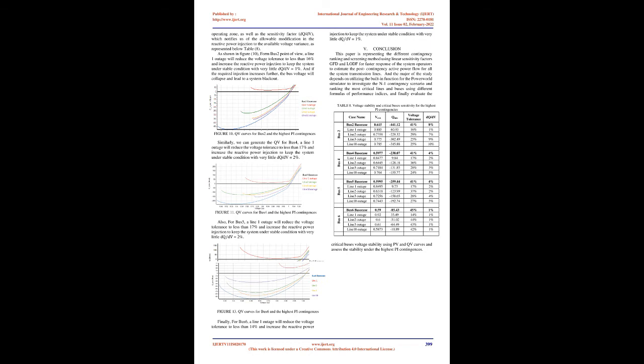A. Multiple contingency ranking. After performing the contingency analysis for each bus outage, which simply represents the multiple contingency scenarios, where each bus connects at least 2 elements in the system, I proceed with the critical bus ranking using a newly developed performance index that combines the active and reactive performance indices presented earlier in section 2, as shown in equation 7 below. PI complex equals PI_MW plus PI_QV.